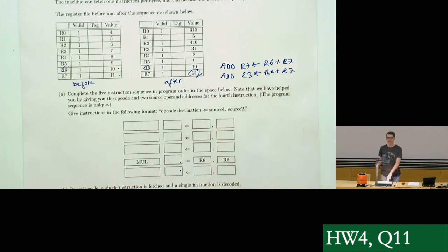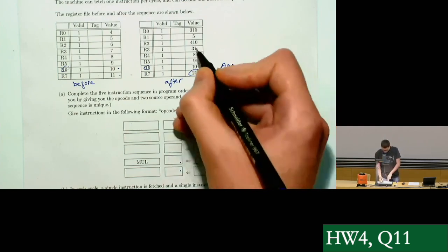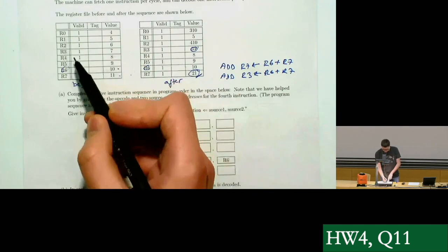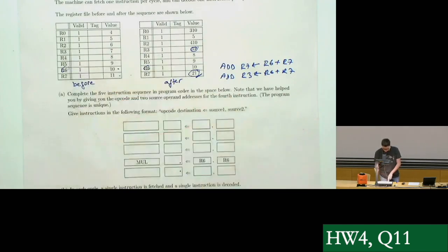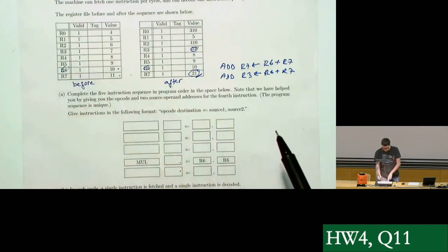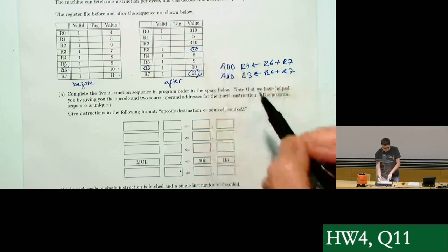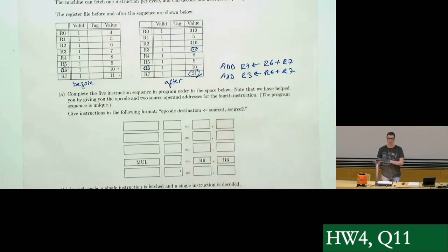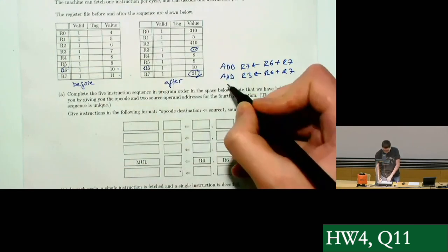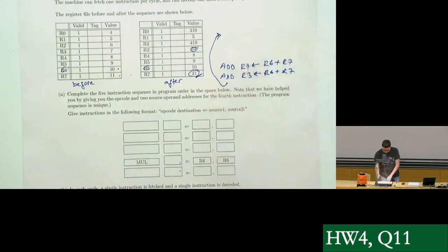So we did that too. Other values that are updated are R0 and R2. For R0, we already calculated 31 here, and we have 10, and we have the multiplication instruction. So we can multiply those two registers and write the result to R0. It will be a bit ugly, but this is the next instruction here.